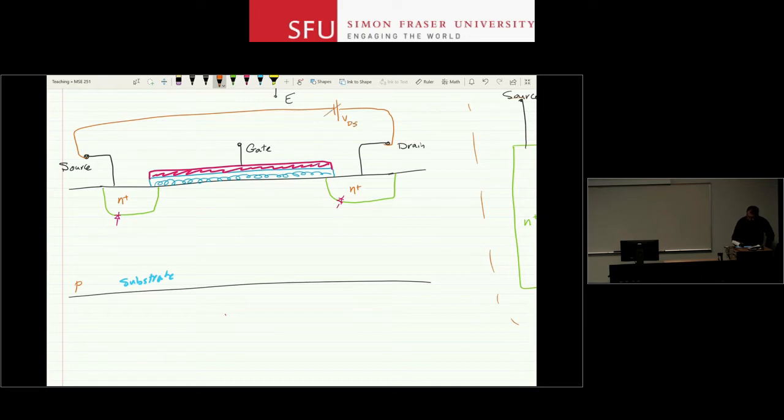It's a very, very small voltage source. So what is small? Let's say 10 millivolts, 20 millivolts, something really small. And if I connect this voltage source between the drain and source of this device and try to measure current, I do not measure a noticeable current.